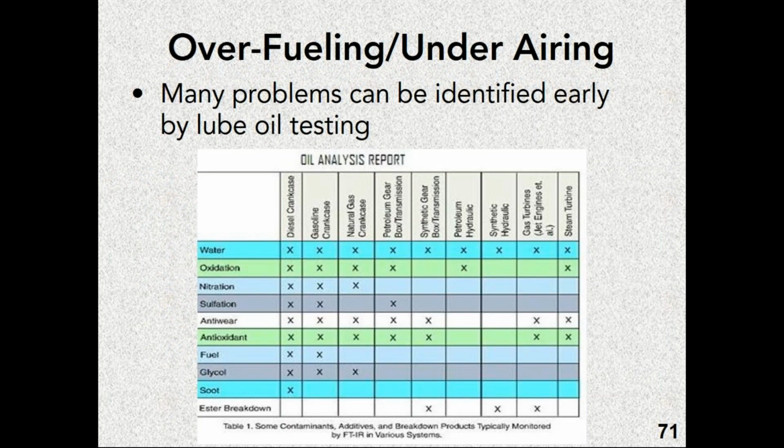There is one way you can determine how an engine is functioning without taking it apart. Now, good mechanics will be able to tell you what an engine is doing, but a lot of times historically, mechanics have used the emissions, the exhaust, to actually make the call as to what could possibly be going wrong. So when an engine puts out blue smoke, for example, generally you're burning oil. When an engine puts out white smoke, generally you're probably burning coolant.